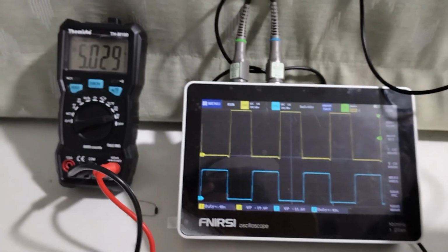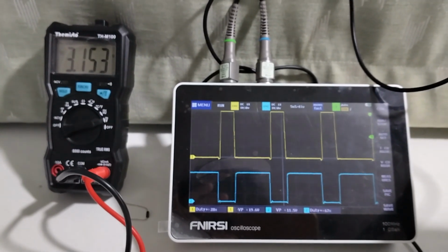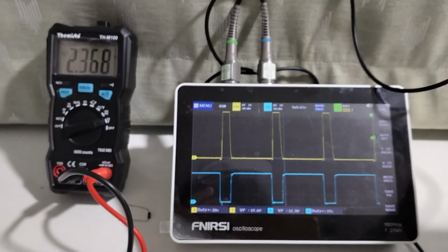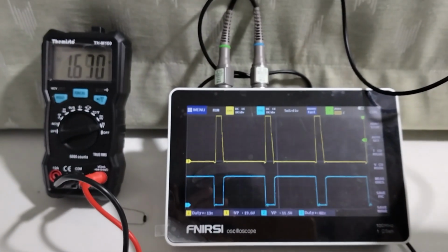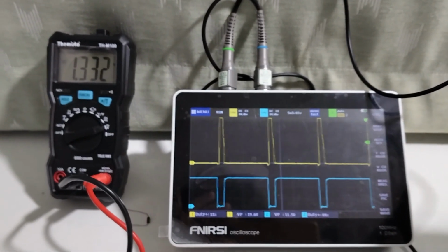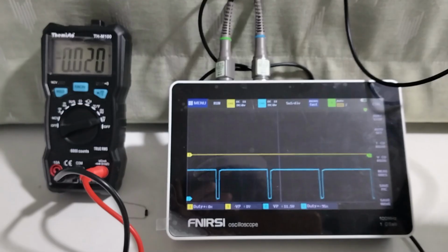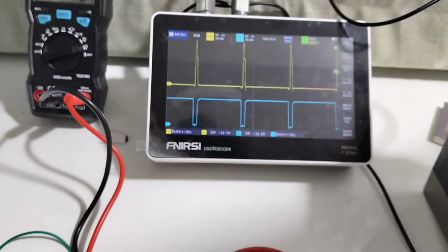I'm just decreasing the duty cycle now, can bring it back to 0. So you can see 2.5% duty decreases, and this is up to you. You can even give 1%, or you can give 10%, and that's the beauty of using an encoder. You decide how much duty cycle you want to reduce or increase. So back to 0, and we have 0 volts. So let me switch this off. This was the whole point of the synchronous buck converter here.